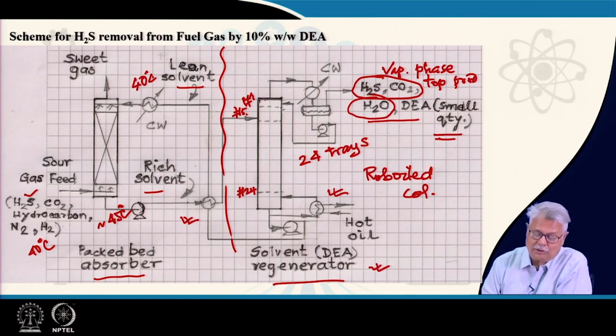In your distillation column here, the bottom temperature is higher than the feed temperature. Quite naturally, there can be some amount of heat that can be transferred from the bottom stream here to the column feed, and which is definitely done in this particular heat saving scheme. Basically, it is a heat conservation scheme.